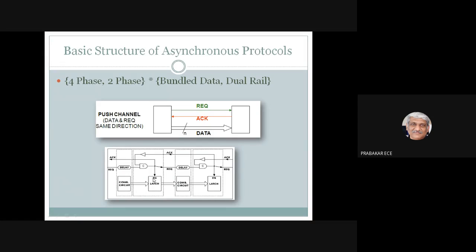This latch will be enabled only if the output from the C is coming, and the output of C is determined by the output from this delay, and another output coming from the next latch. This is because it has to ensure whether this data is ready to be taken by the next combination circuit. So this output will also be coming here, and this delay output will be coming here. These two are processed in the Muller C element, and only if this has completed its process and this data is safely latched here, I will get this output here, and this data will be latched here. Then this data will come out from this latch, and this signal will also come out. There is a combination logic again, with an equivalent delay. By the time this combination logic manipulates the data, this delay process will be over. And this will be given to the next latch only if this delay is processed and the next section is ready to accept the data.